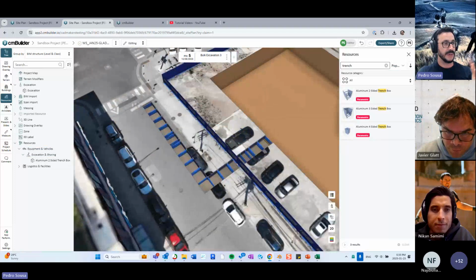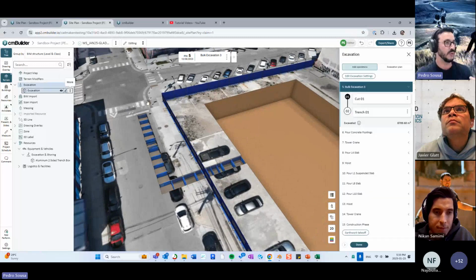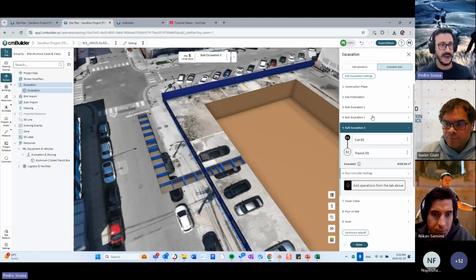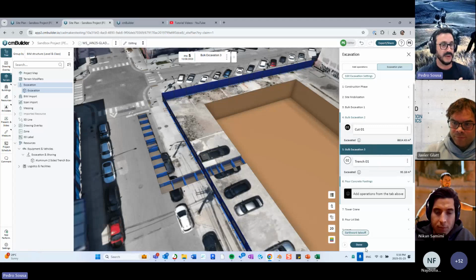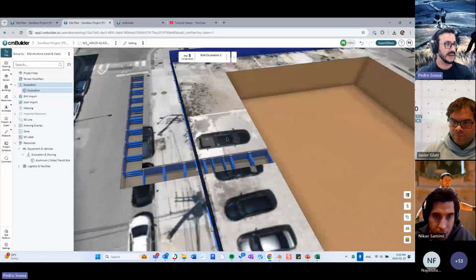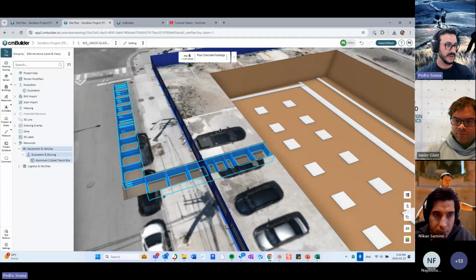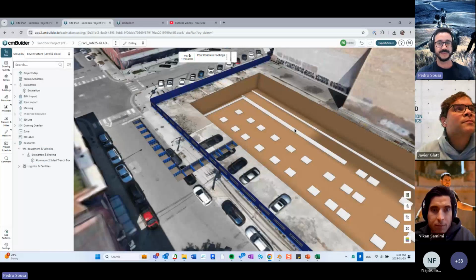Of course, you can place these elements in your timeline. The trenching itself, you control by moving these cuts throughout the timeline that you have on your milestones over here. So I can have my trench happening on excavation number 3, for example. When I go back, that trench is not there, and when I go forward, it's there. The resource that you place, you connect to the timeline the same way that you connect everything else. There you go. So this is our trenching tool.